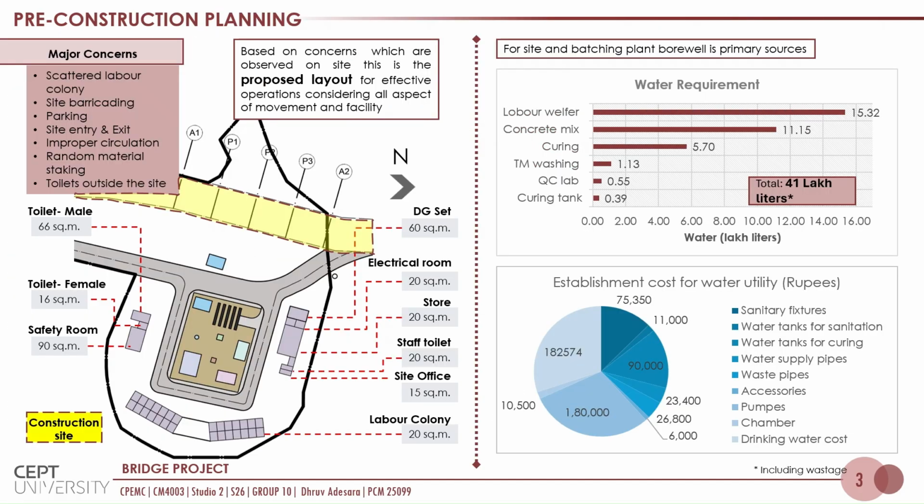Based on the observations like poor labor colony planning, random stacking of material, inappropriate site barricading, and other findings, we have proposed this site layout, which has a dedicated labor colony with an attached resting area, a dedicated site entrance and exit for proper circulation, and material stacking areas.